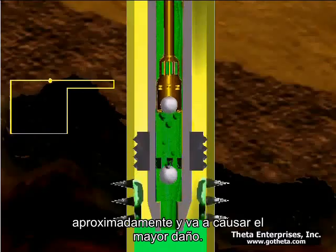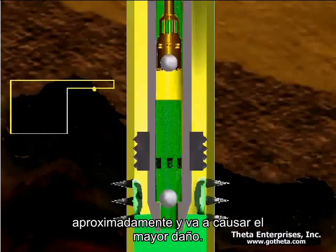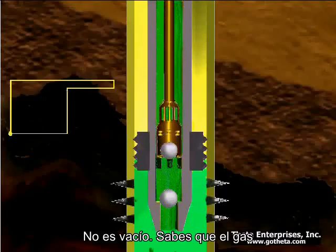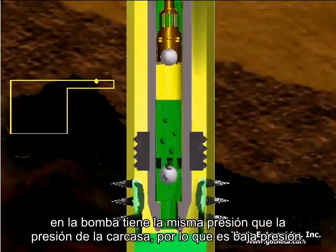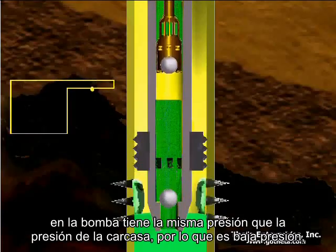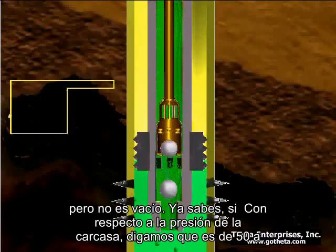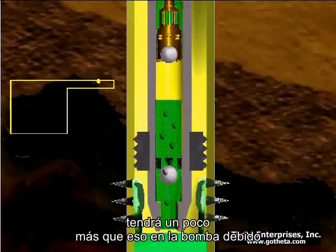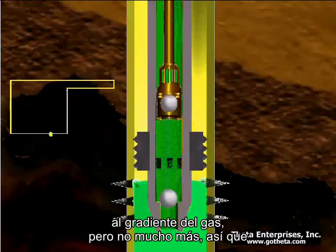Would that be considered a vacuum inside, because you're not compressing anything when the ball is dropping? It's not a vacuum. The gas in the pump is at the same pressure as the casing pressure. So it's low pressure, but it's not a vacuum. Like if your casing pressure is, let's say, 50 or 60 psi, you're going to have a little bit higher than that in the pump because of the gradient of the gas, but not a lot more.